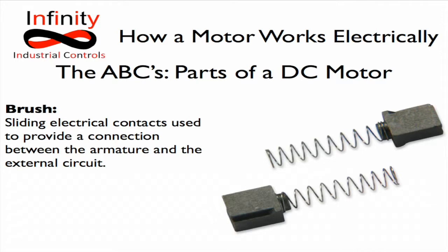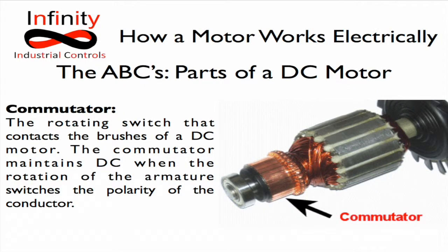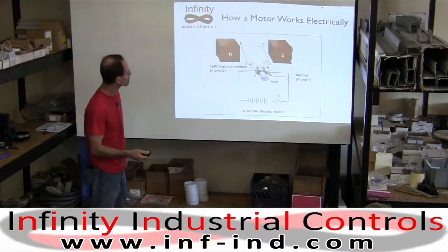A lot of you guys probably changed those out before. They have springs on them so they maintain tension against the commutator so that it makes contact. That's the commutator here. And you can see it's a bunch of like plates separated by insulators.